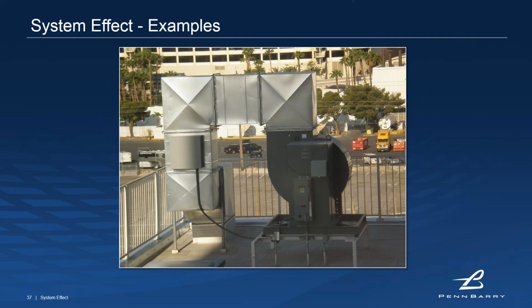And if you imagine that you expand that air too quickly, you'll get cavitation, you'll get severe turbulence, and all those sorts of things. So really what we want to do, whether it's an inlet transition or an outlet transition, is try to avoid making any kind of change in the profile that's more than 7 degrees off of either side. And that just has to do with the rho value of air and its ability to change directions while staying in a semi-turbulent or a laminar flow. Hopefully that answers the question.